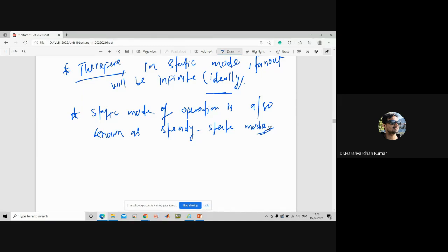In case of transient response, it is degraded. Transient means giving a rising or falling pulse, which means that at any point of time, you are charging or discharging the capacitor. If you see the switch model of the MOS transistors, while charging the capacitor, you get logic 1 in the output, and while discharging the capacitor, you get logic 0 in the output. So at any point of time, you charge or discharge a capacitor.